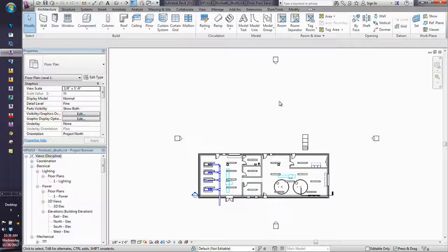So if I'm working in a multi-story building, I don't just have them by engineering, I have them also done by HVAC first, HVAC second, HVAC third. Okay? Do you ever have a project where you have a lot of different users? How about a project with multiple buildings? In our water treatment plants, I've got them set up so that all of the buildings have their own Worksets, and then they have their own discipline within that. If the client has a building number list, we'll use those building numbers so they know how everything's supposed to be sorted and organized. So I might have building 19 HVAC, building 19 architecture, building 19 structure. We break them all up that way.